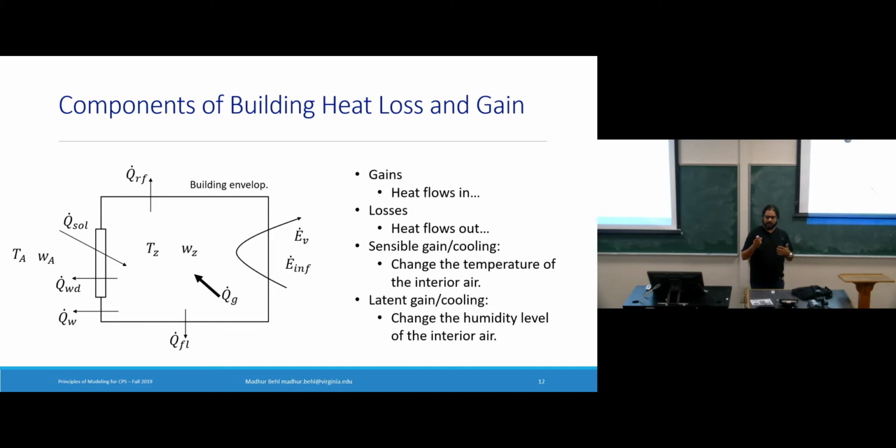And eventually that will also dictate thermal comfort, or we can write an equation for that part of the HVAC component as well. But we will not look at latent gains for the most part in this course, because I want you to take away the main principles, and this shouldn't turn into a building thermal dynamics class. So we'll mostly look at just sensible gains to keep things simple, and essentially we'll look at the flows which influence these sensible gains.